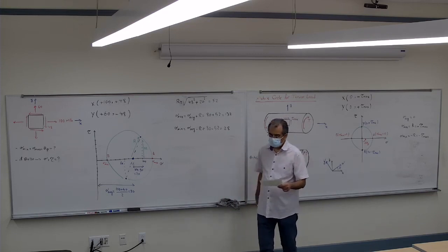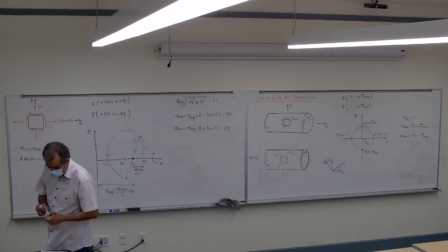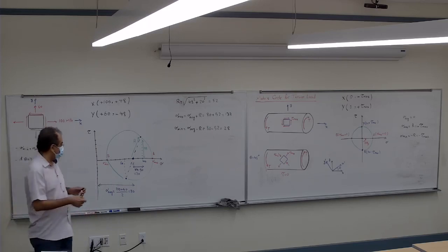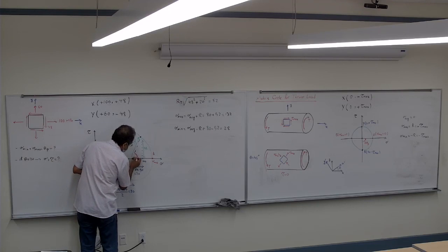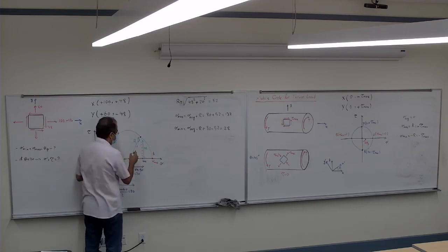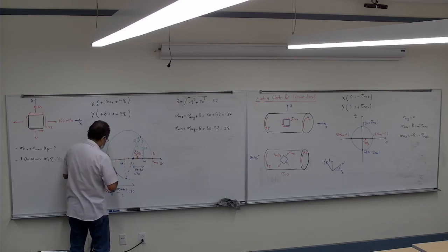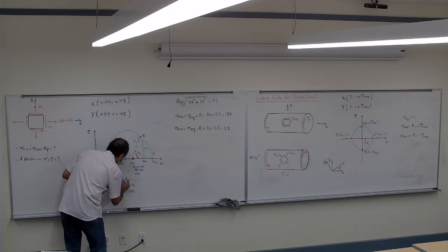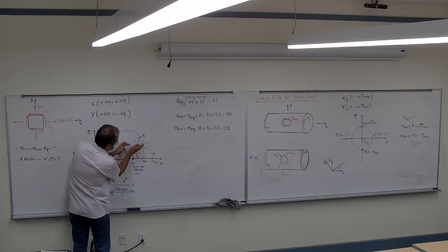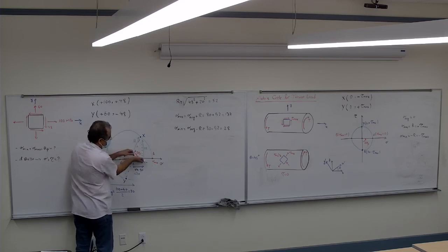Now, what's the location of that? So look here, in this case, the 2 theta p is like that. It's going to be clockwise. So from the point X, remember that's the point X, that's the point Y. So from point X, I come to the sigma max. So I have to rotate this much clockwise.